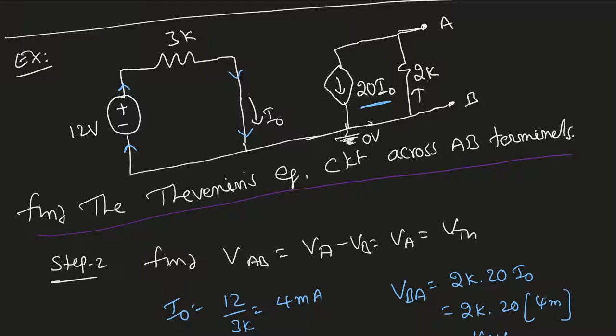So step 1, we need to eliminate the resistor or any element across which we need to find the voltage or current. In this case, we do not have step 1 because the question already gave us the open terminals. So we don't need to eliminate any element here. All we need to do is convert this circuit into a voltage source, which is Vthevenin, in series with a resistance, which is Rthevenin. That's all we need to do. So I'm going to move to step 2 right away.